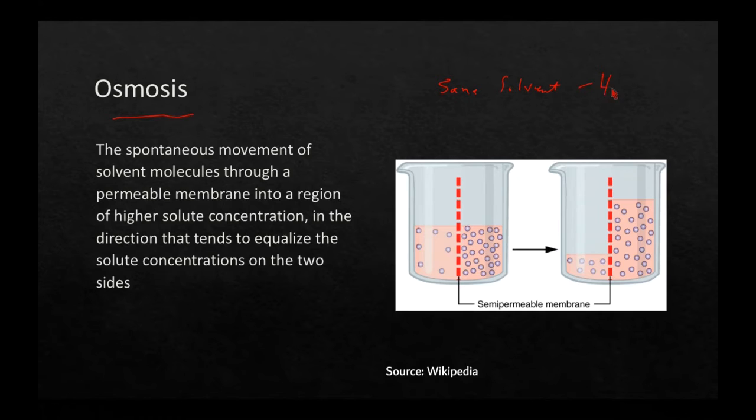The solvent, of course, is water in our case, and the solute is a combination of calcium ions, magnesium ions in the case of hardness constituents, sodium ions, maybe some iron ions, whatever. So we have all these ions, but it's basically the same stuff on each side of the membrane.